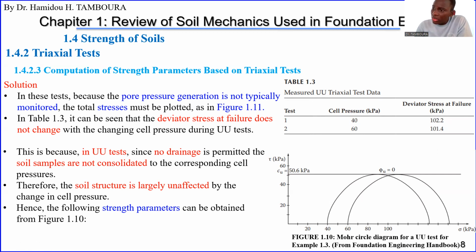So it means the soil sample you have in your test is not consolidated. The soil structure, the soil particles, they are not affected at all. No matter the load you are adding, the load is taken by the water because you are not draining the water.